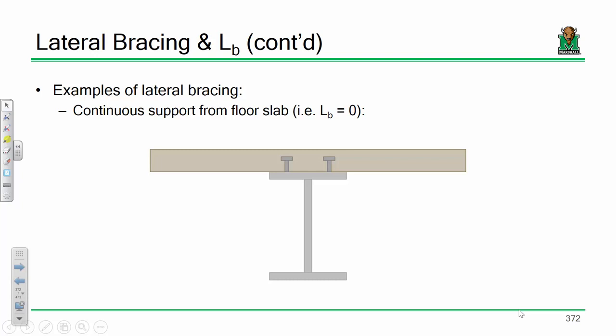That's a good question. The question was, how far apart do you space them? I'll say two things. Spacing shear studs is a discussion in and of itself. It's a function of one of two things, either strength or fatigue: whether or not the studs have adequate strength to transmit that shear, or whether or not they're going to behave well during fatigue. In bridges, you've got more than enough strength. Strength's not an issue. It's always fatigue.